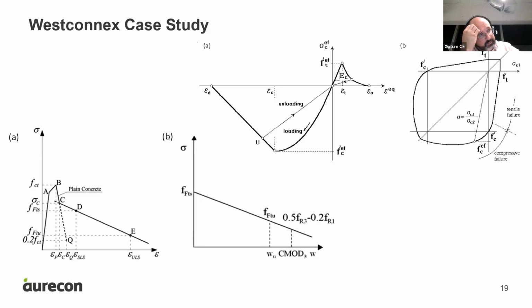It depends, but I know it's in the order of over $2,000 per ton or something like that, but I can't give you the exact number. When you compare the high performance fiber to a more conventional fiber, all we need to do is reduce 5 kilos in the fiber counts and it would pay for the higher performance fiber. With the conventional fibers, we are using up to 45 kilos. When we manage to drop to 35 kilos, that more than paid for the extra cost of the high performance fiber and actually provided savings.